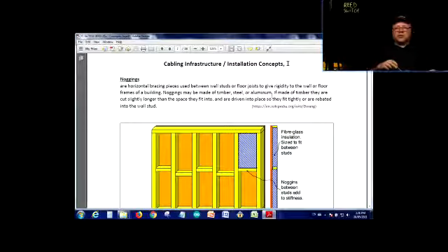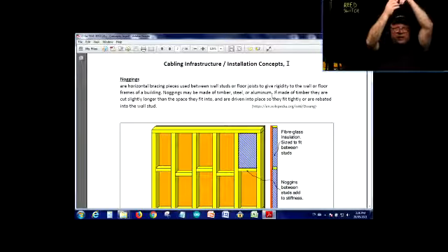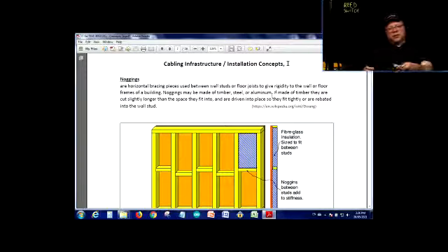In commercial buildings, instead of a wooden frame, you're going to see a steel framing sometimes. Quite often, when you have a warehouse setting or something like that, in the steel studding or steel framing, you might see that there are not too many horizontal studs, if at all. So you can just run the wire right from the very top to the very bottom. You can drop a piece of chain on a string, drop it down, and catch the chain with the magnet, pull it out, and you have a string. Then you can tie the wire to the string, pull it down, and here's your wiring. So that's when the steel studding is involved.